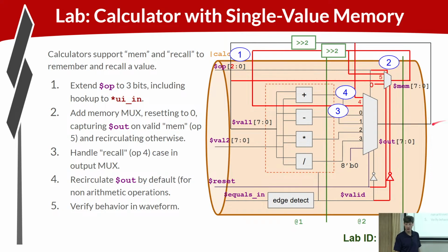So I'm choosing to loop that around on a 2-cycle loop because the operations are at least 2 cycles apart, right? So when I get a mem operation, the value from the calculation that happened 2 cycles ago is stable, right? I'm not going to change that the next cycle. So this could be a 1-cycle or a 2-cycle loop. It'll be stable in that window.